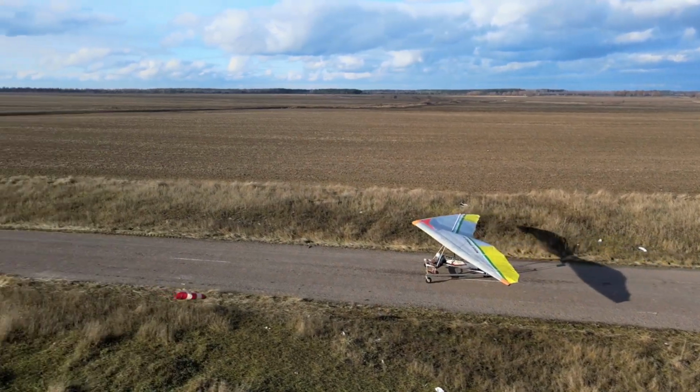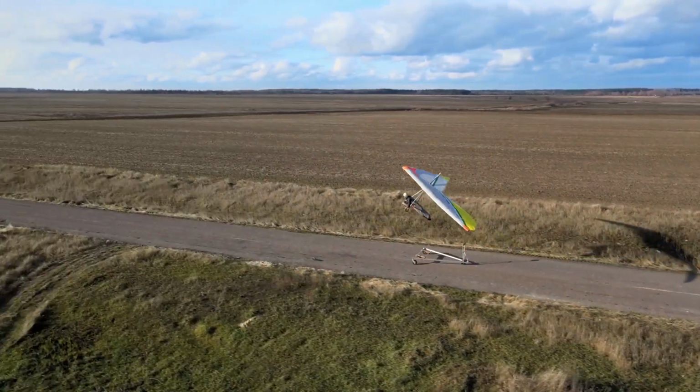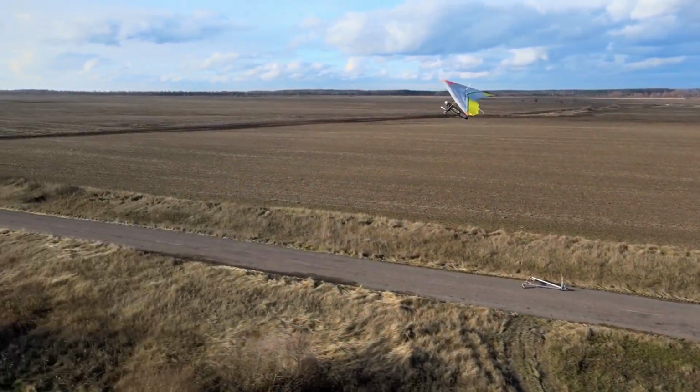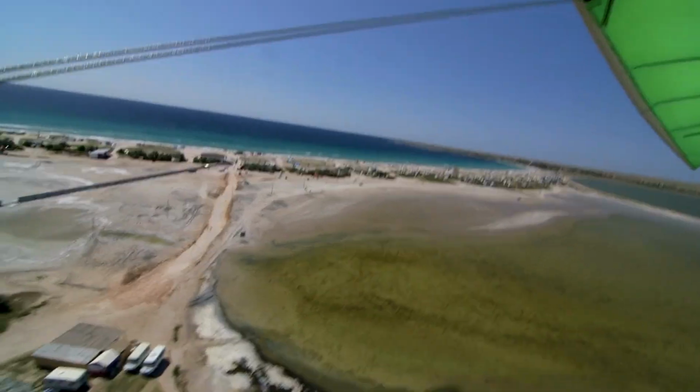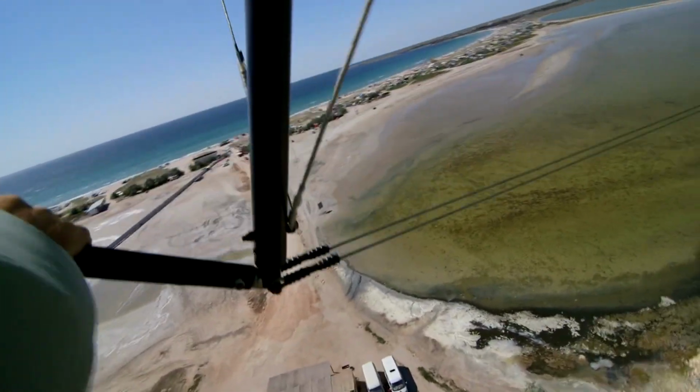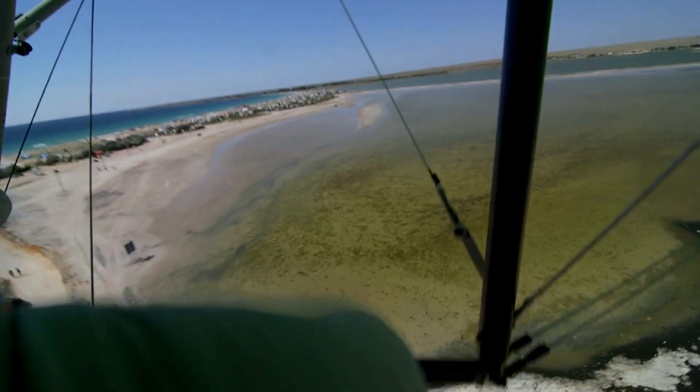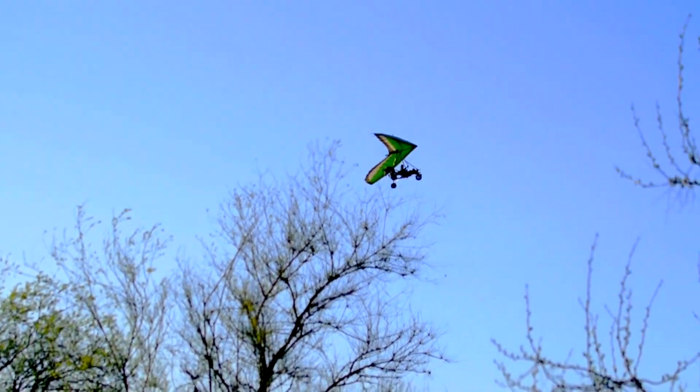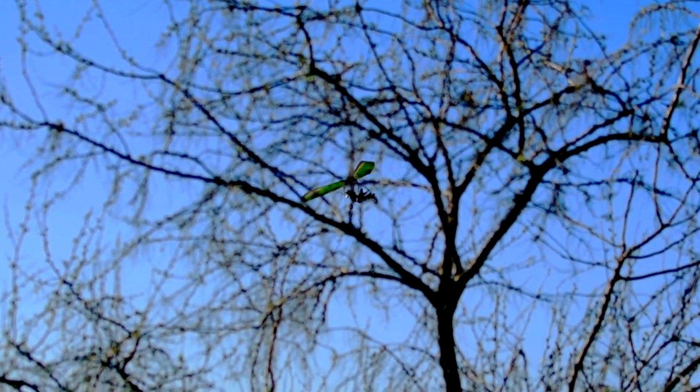Finally, lift production involves the airfoil shape and the downward deflection of airflow due to the curvature of the wing. The lift distribution in WSC wings differs from traditional elliptical distributions seen in airplane wings due to wing twist, resulting in a higher lift at the center and less at the tips. Mastering these aerodynamic principles is key to navigating the unique dynamics of weight shift control.